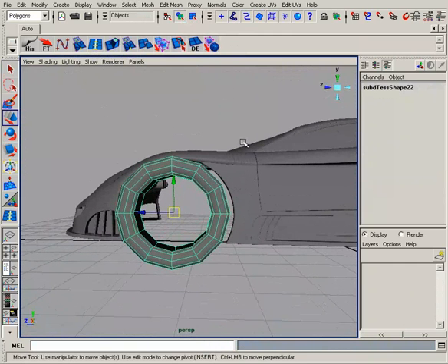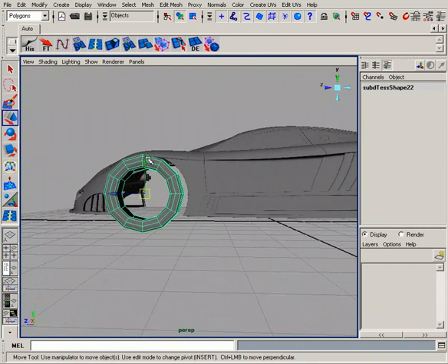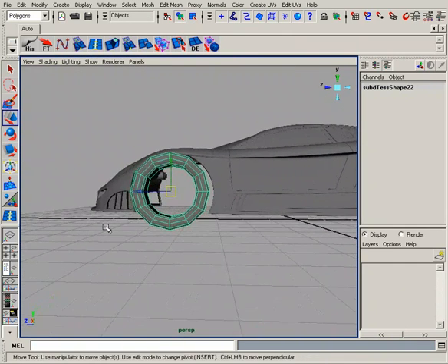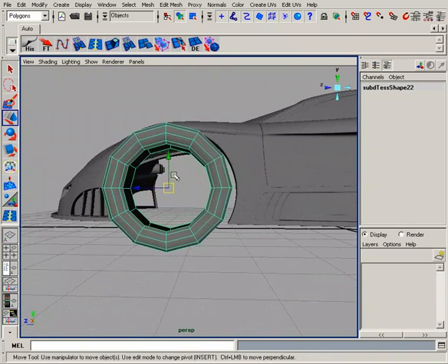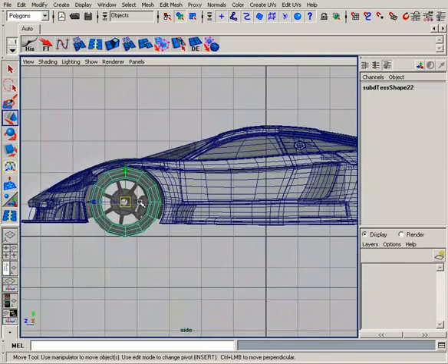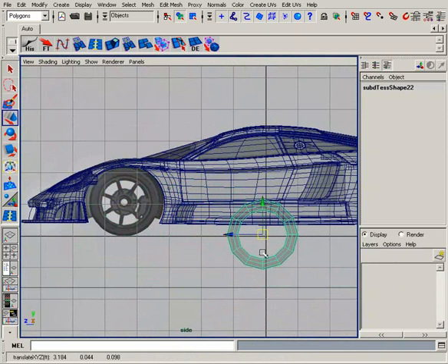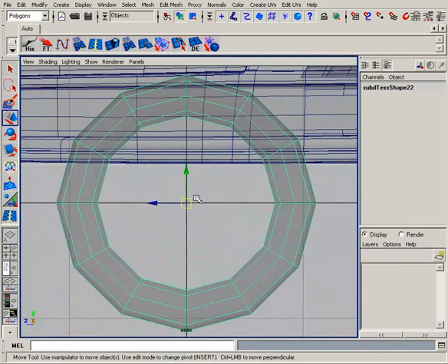So now we need to come in and start working with the rim. Now to fit all these things together, building a tire like this, which is obviously the cylinder shape and it's got a center, and we're building all these things off of a center point. When we do that, I like to move that over to the origin. So we've got the width there, so I'm just going to snap this to the origin just so we can have a center point that we know is there.